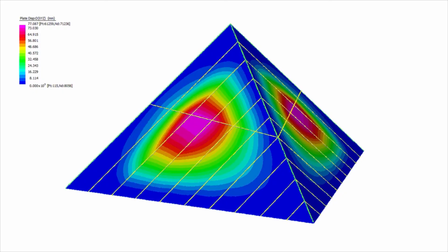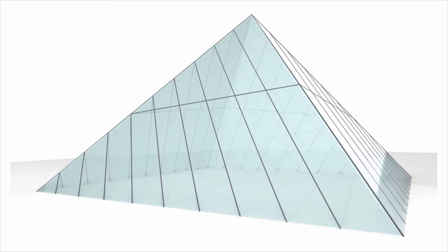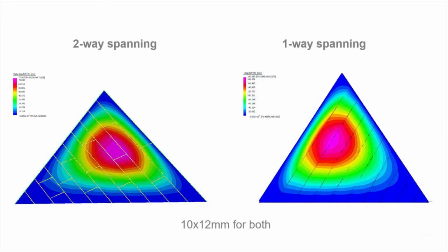And so we get this huge increase in stiffness, a reduction in the panel thickness, and arguably a glass structure that's within fabrication limits and has no steel or backup structure required at all. And just comparing the efficiency of this two-way spanning structure with the one-way spanning structure, we see that, given the same assembly, it's drastically stiffer than the counterpart that I showed at the very beginning.